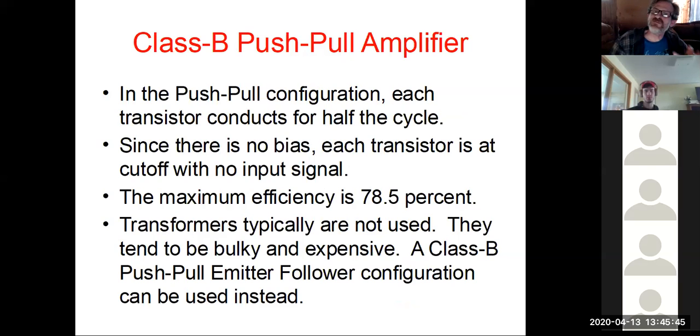So in classic push-pull configuration, now remember, push-pull: on, off, on, off. So whenever you hear that term, push-pull, just think sink and source. What that means is, for electrically driven, so on and off, one is sourcing and one is sinking. And what sinking really means is I'm acting like a ground point, if you will. It's not really, but it would almost be a way to think of it like I'm a virtual ground. So one is sourcing, meaning he's driving out, and one is sinking, meaning he's acting like a ground or clipping,